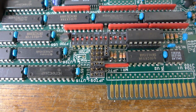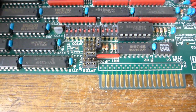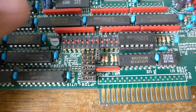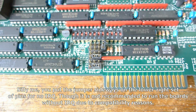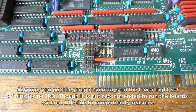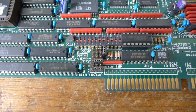This jumper here specifies which interrupt to use. Right now it's set to interrupt 10, which is also the default, or you could set no interrupts by putting it on these pins here. But I don't recommend running the DTL-H2000 without an interrupt, because I think some features would not work correctly or not work at all, or lead to instability.